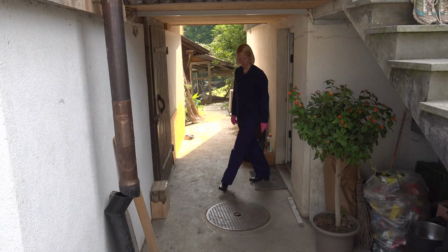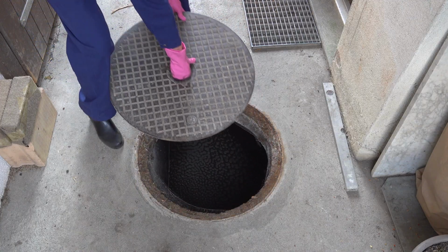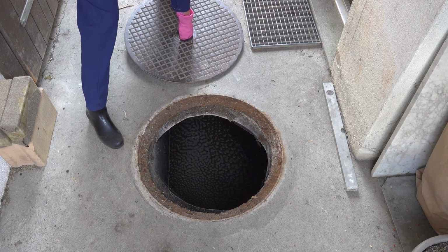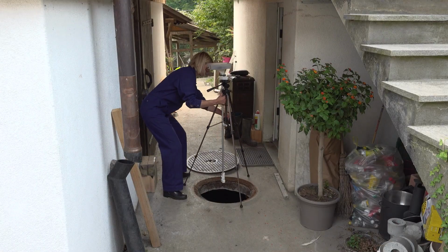When arriving on site, first identify where the Volaser can access the on-site sanitation containment. Open the access port to the containment if there is one. Extend the tripod into the operating position.